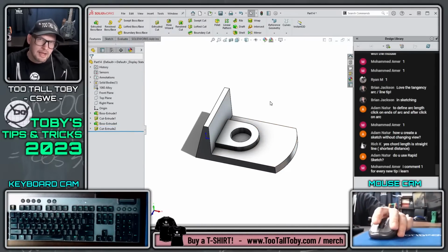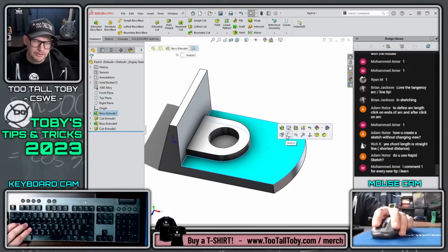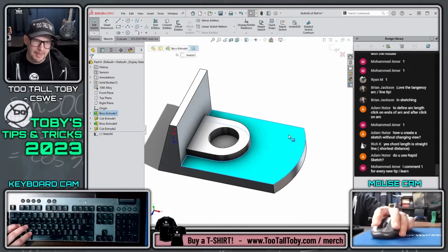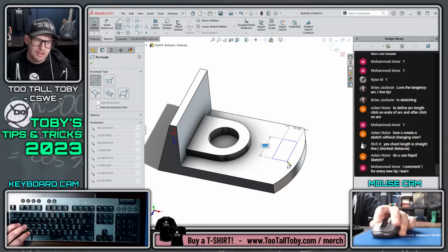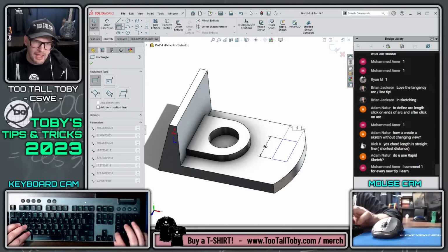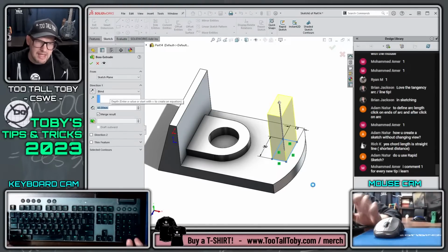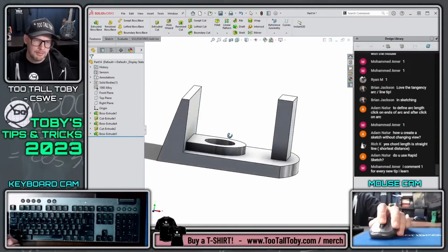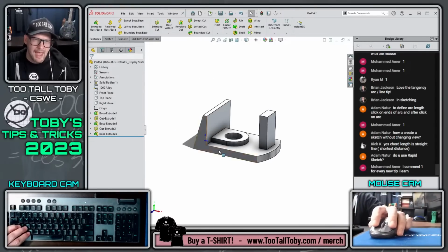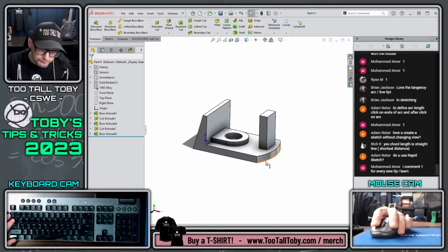So this is really a great way to save time when you're working through SolidWorks. It's one of the first and easiest ways: anytime you go to create an extrusion, you get in there, fully define your sketch, and then S key, extrude, type in the value of the extrusion, 60, enter, enter. Boom, you're done with that feature. Just a really excellent way to start saving some time in SolidWorks.